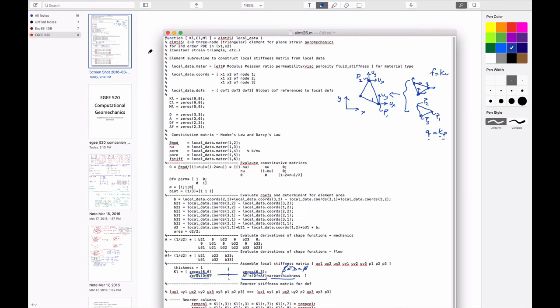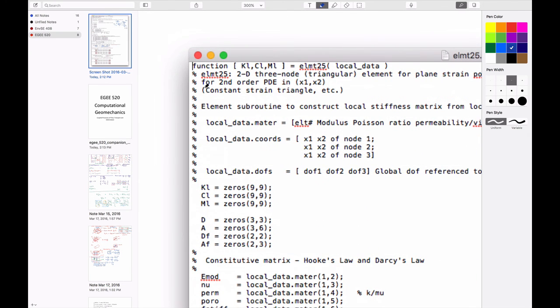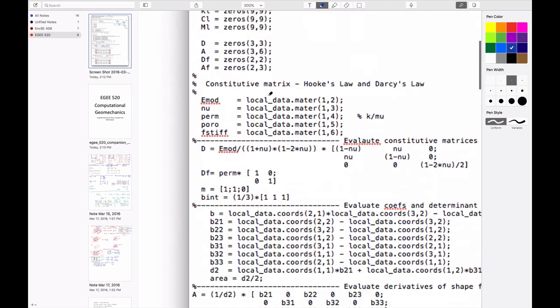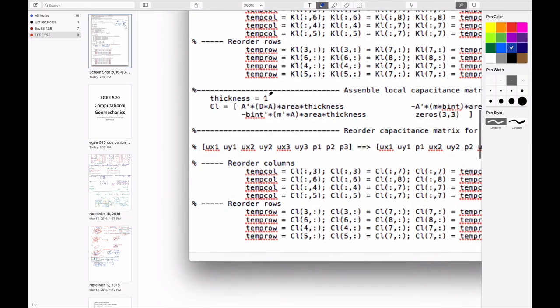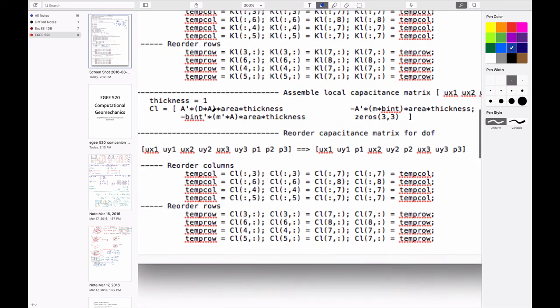And if we look at those, this is, if you like, the part that operates on the rates of change of something, like the damping matrix, and this operates on the second derivatives, d2u dt squared type terms in Newton's second law, F equals ma. And if we look for the CL matrix, this is it here. And you see exactly that behavior.